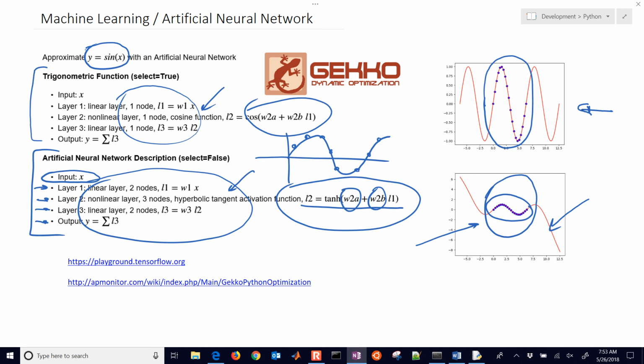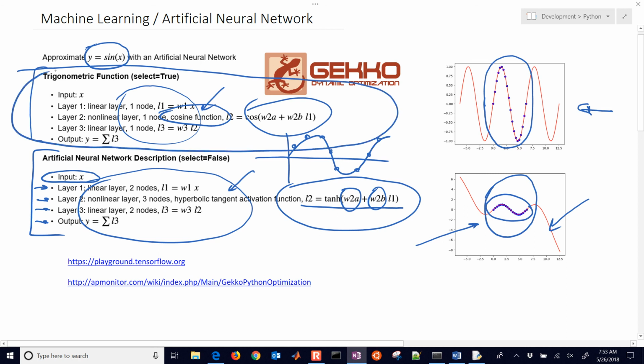We're going to continue to develop this, especially for what we call hybrid modeling, where you have some knowledge of the structure. This would be an example of where we would use hybrid modeling. Maybe we have things like material or energy balances that we can enforce on the problem so that we can extrapolate better outside of the training data set.